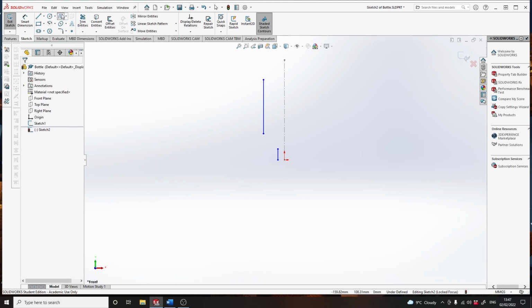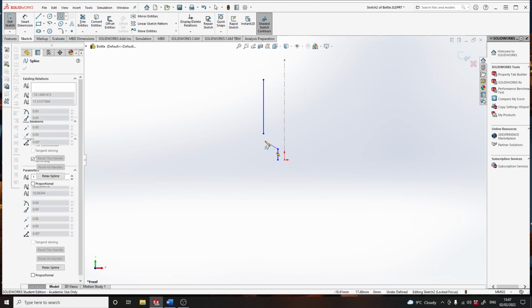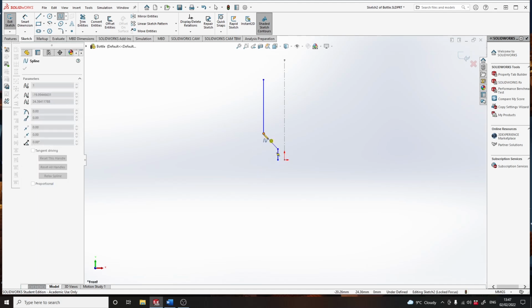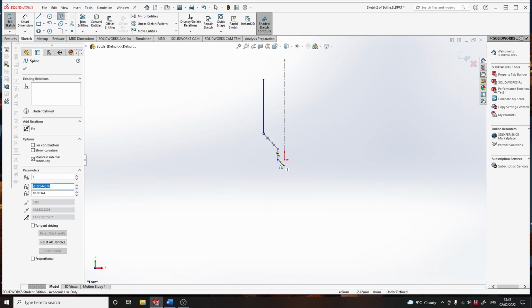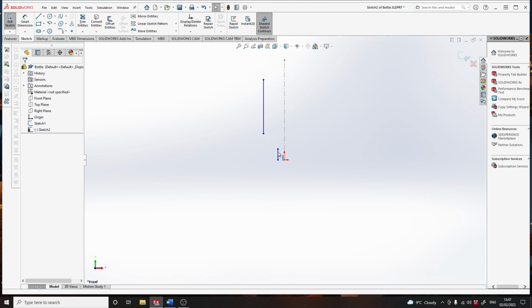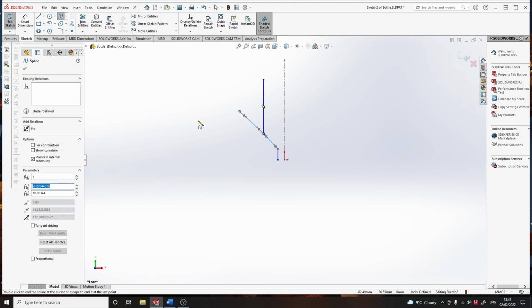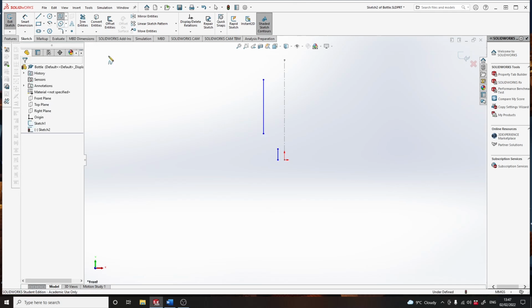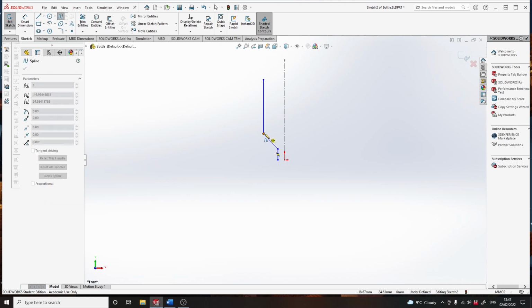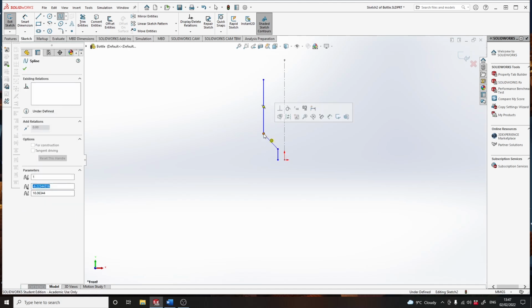If we now add some splines, the wiggly one there is a spline, and we can just connect those two together. You click it, and then you have to double click again, and that leaves a straight one in there, but these handles have appeared. If you do it differently, you sometimes connect it, and if you move it away you get this kind of wobbly thing, and then if you double click it you'll end up with that. So you don't want that. You want to join the dots up. When you arrive, click on it and then double click to finish.